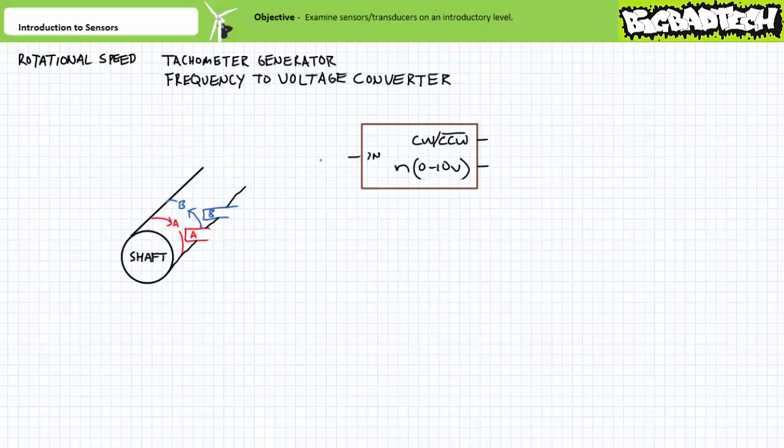First, speed and direction can be represented using two separate pieces of data. Rotational speed magnitude can be represented as previously using a proportional voltage signal. Direction can be independently represented as a digital or logical value.